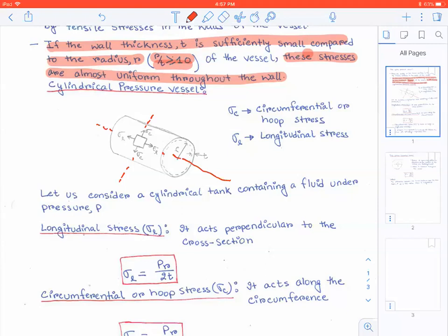You can consider the body of the aircraft to be a thin cylinder, and you can consider that problem as a thin cylinder problem, because the inside pressure is going to exert stress on the material the whole aircraft body is made of. So this is where it comes in handy, and obviously for any pressurized fluid vessel, for analysis of those vessels, you're going to be using this.